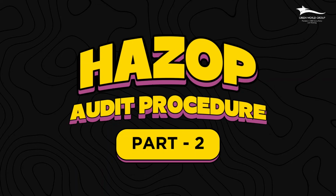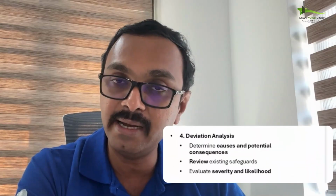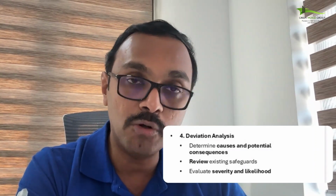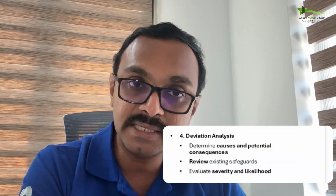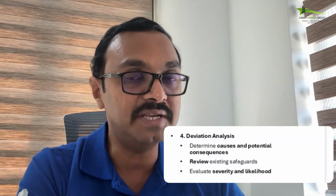Now let's go to part 2. In part 2, we have the fourth step, which is called deviation analysis. What is deviation analysis? For each deviation identified using the guide words, we determine its causes and potential consequences. We also check what safeguards are currently in place and assess both the severity and likelihood of each risk. That's what we do in a deviation analysis.